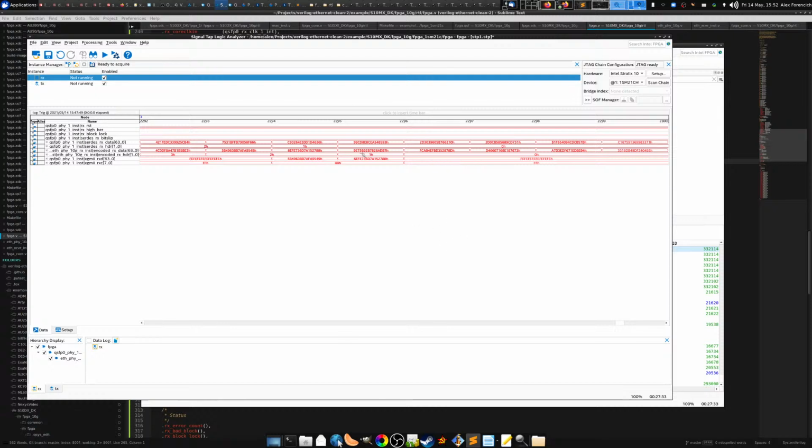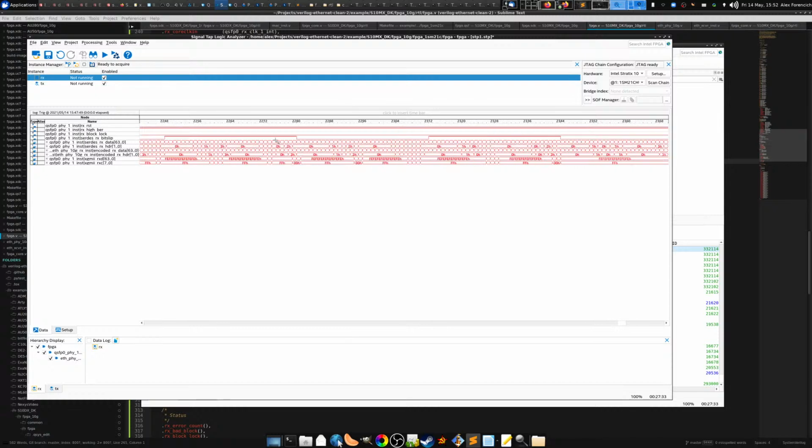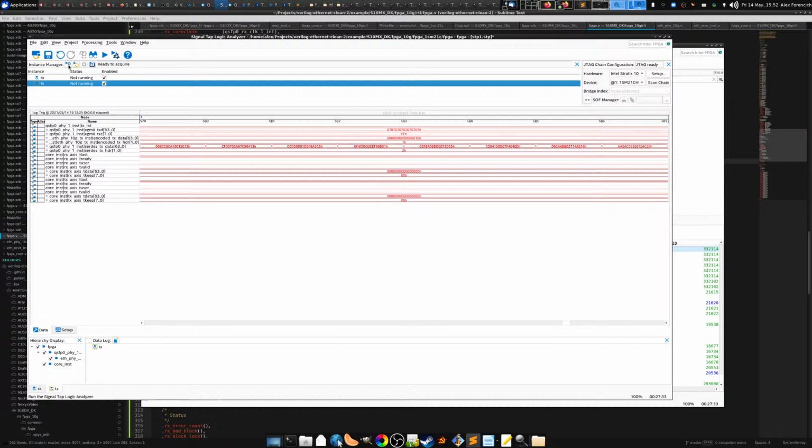So, you know, it's not working. Interestingly enough, the transmit side does seem to be working. So the only thing that we changed there, right, so previously it wasn't coming up, this time it is coming up. So that means that we now have the bit ordering correct, because last time we weren't getting a link, we are getting a link now. So the bit ordering is correct, but there's something else that's causing trouble.